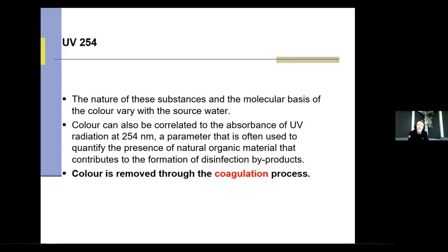This is a fairly new technology. We started using that. At my plant, I have 2 of them. So I measure the amount of organics coming into the facility, and now I can set my treatment process. But I also check it on the way out, so I make sure how much organic removal or color removal I did, and I can measure it using this UV254.